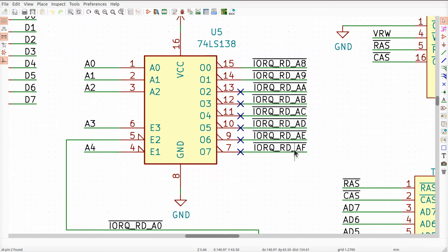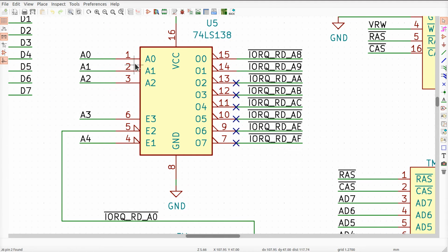So these are fully decoded. All 8 address lines are decoded here. So in this situation, and mostly because this A3 has to be high, right? So we don't actually have one that says A0 here, right? Do a truth table, you'll see what's going on. Pretty sure I'm right here.